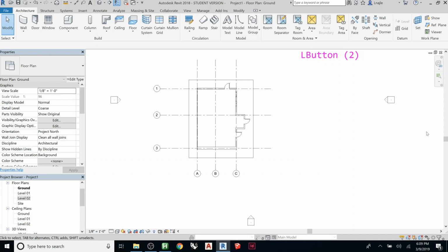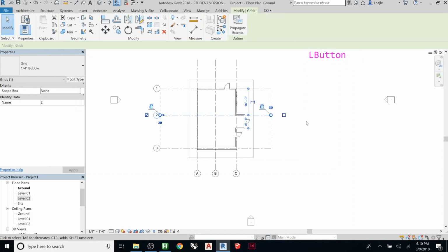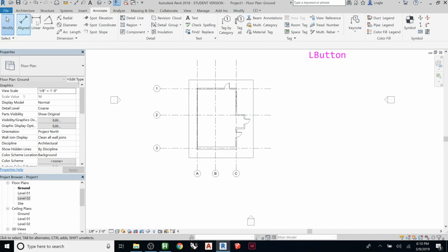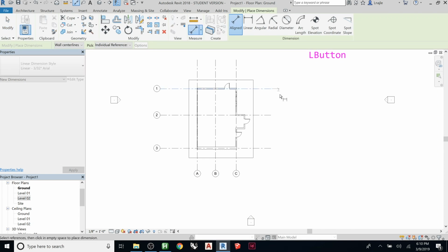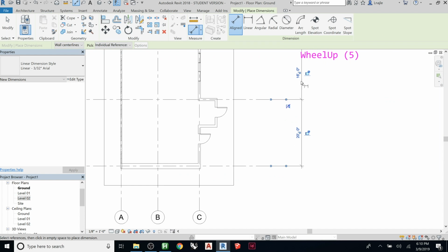This next thing I'm going to show you works with sort of any kind of geometry. It can be doors, windows, columns. It's basically a trick to get equal spacing on repetitive kind of things. So right now we have, let's say I just kind of drew these in place. If you go to annotate and you grab, let's say an align dimension, and I go boom, boom, and then click here, boom, and then move this out. Notice how it's telling me this one's 16, this one's 20, and it's saying they are not equal.